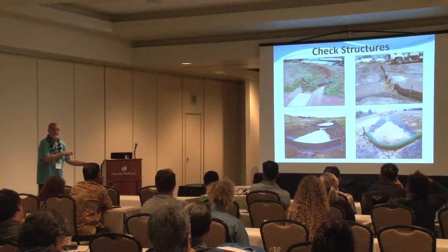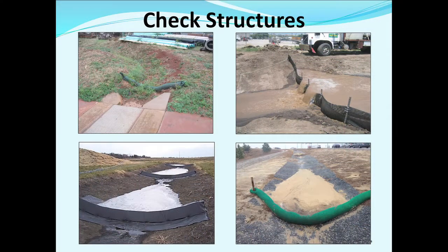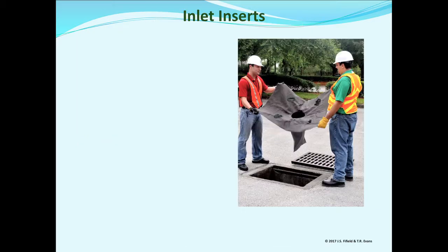Did you design it rightly? Did you do shear stress? Did you do velocities? Did you use something called, remember Manning's equation? All these nasty things that we tend to forget now that we're out of school. You've got to keep them, incorporate them.